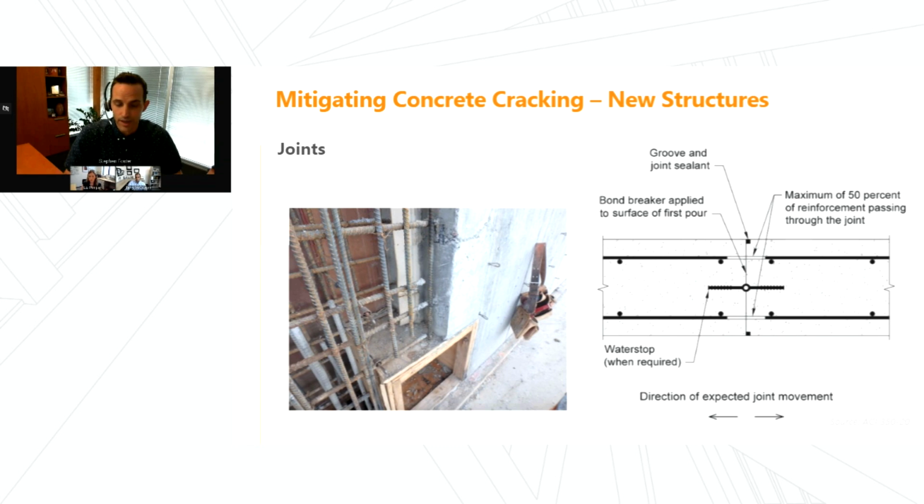But maybe we scan and evaluate cover depth in the rest of the locations and realize, oh, all the other bars are actually half an inch deeper than this location, and it's kind of a one-off. Or is it an indication that actually multiple other areas are likely already starting to corrode? They just haven't manifested yet into visible surface damage. So doing that assessment will help identify how many other areas are potentially already corroding like this, and how long might it be until something else manifests on that column. So doing an assessment will definitely help evaluate that, and forecast how long it will be until other locations look the same.